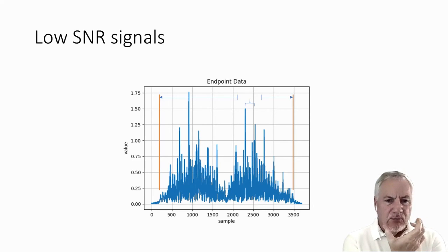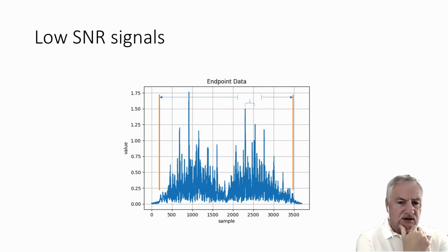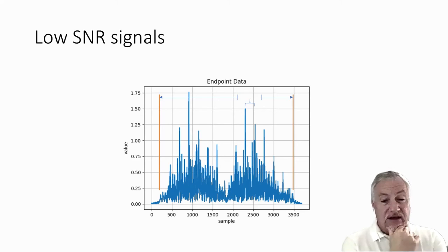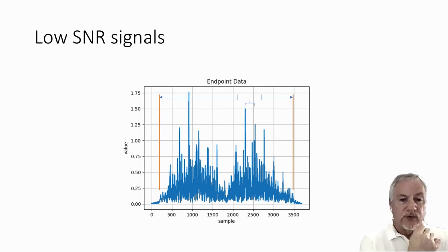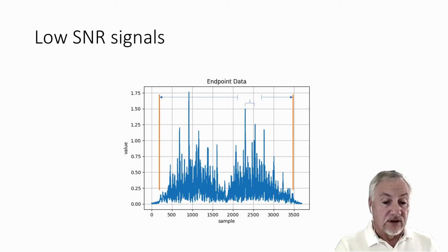So we create a margin, and you see that margin above the bracket showing the 2 highest peaks. There's a margin in which we don't do the summation. We will start on either side of that. And when it's in the center, that works pretty well. But in this particular case, it's off to the right. And the way we had to address that was by increasing the summation window.